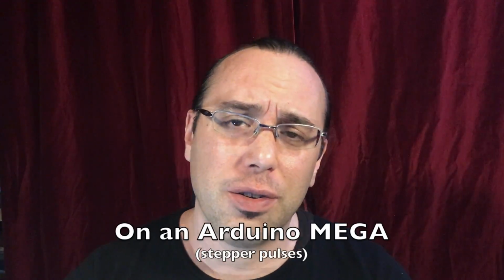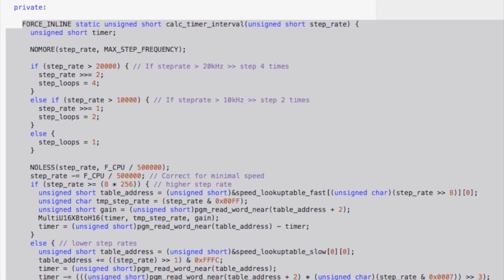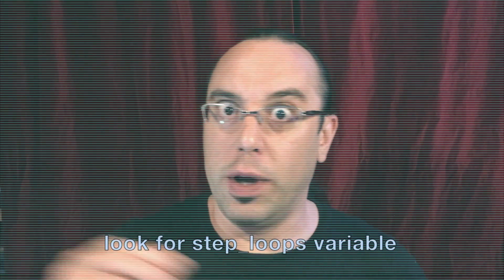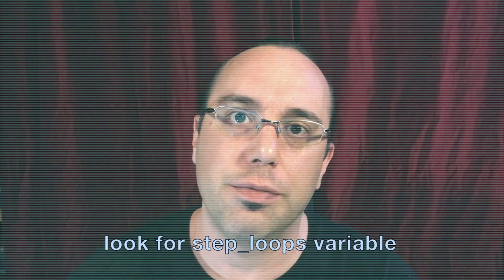If you're familiar with the inner workings of Marlin Firmware, you know that the fastest we can work with is 40 kilohertz. Now, if you've ever wondered why we can only work with 40 cycles a second, in terms of stepper pulses, I mean, the board works off of a 16 megahertz crystal. Why isn't it so much faster? Well, the pulses going out and the interrupts coming in, the actual hardware interrupts, have to be extremely precise. We can't just kind of math it out. It's tied into the actual hardware timers, and that is tied to the system speed, but it isn't equal to the system speed, obviously. And I know I greatly simplified the timer interrupt issue. Sorry. The nerds out there are going to come at me with pitchforks and torches.